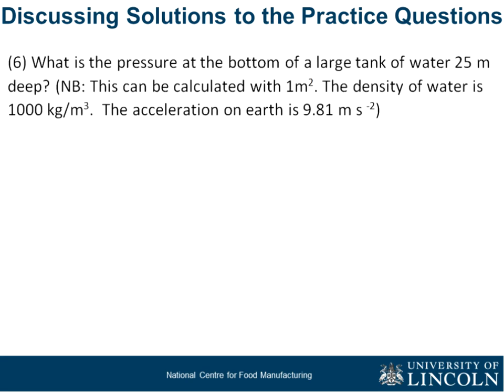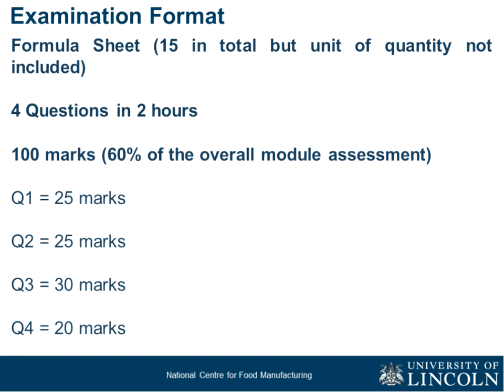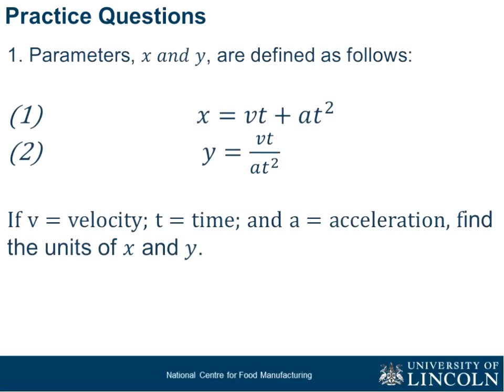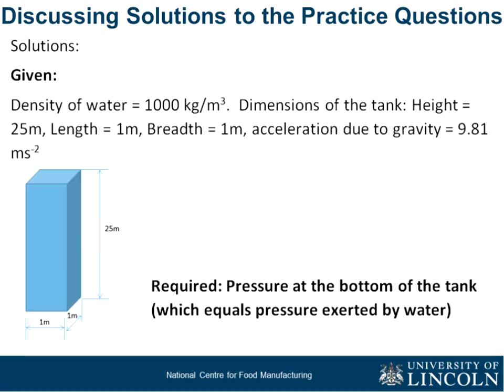I'll go back to that slide so that you can understand. Yes, here I told us that pressure equals the force over area. Now remember I said weight the other time, because force or weight, they mean the same thing. Don't worry about that. Now the pressure is force or weight over area. So can you see force here? Force and weight. So the pressure can be weight over area. So going back to that question now, we have our pressure to be force over area. So here all we need to do is to know the weight of all of this water.